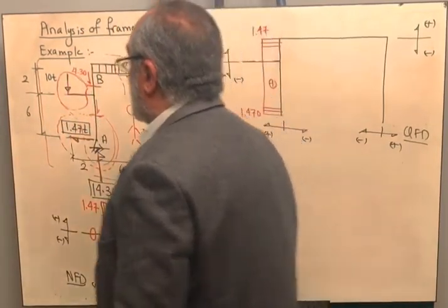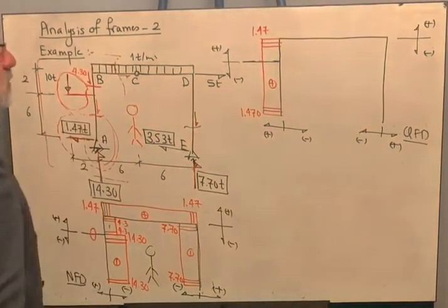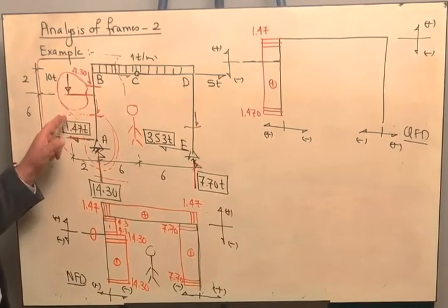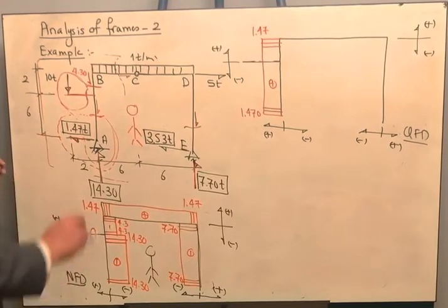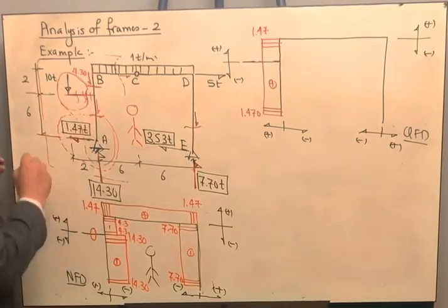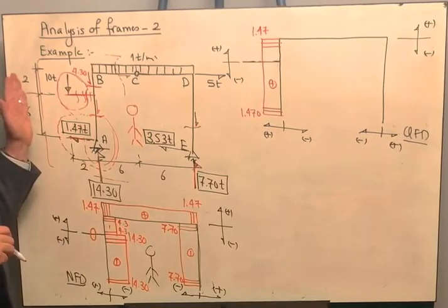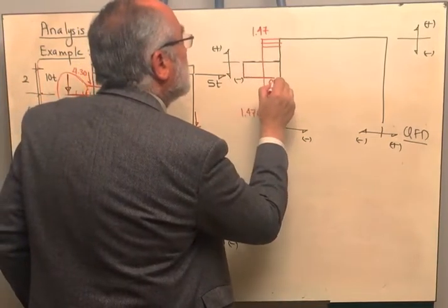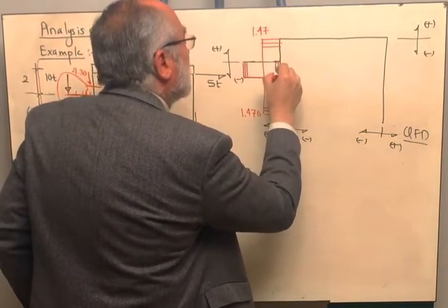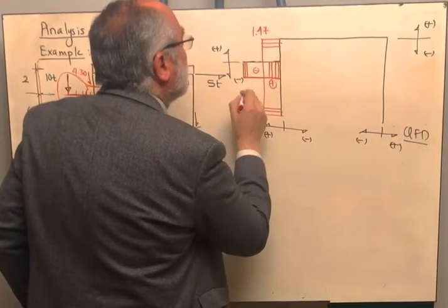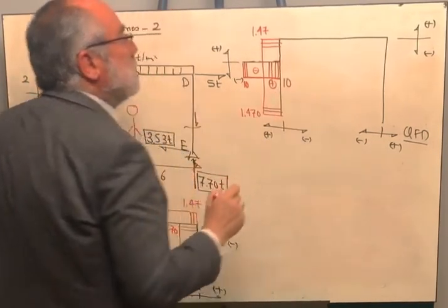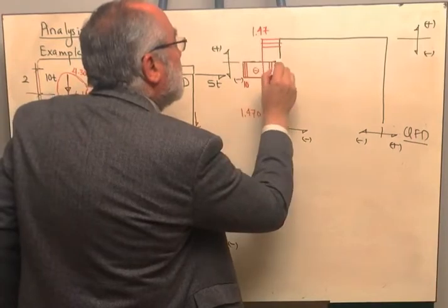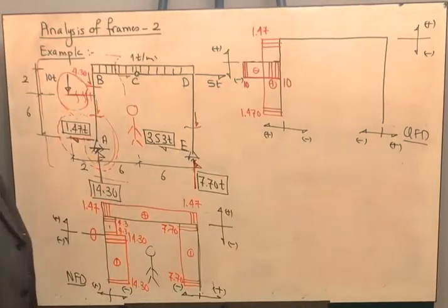Very good. Right. For the cantilever, I will start from the left. On my left-hand side, I am having a force of 10 ton downward. It is negative shear. If I'm taking a section here, or a section here, or a section there, and only counting the left portion, I still have the 10, which is negative. On this datum, it will be drawn below the datum like this. Don't worry if you are having interference in the diagrams, that's something normal in our work. So the central line or the datum is drawn in black, and the magnitude of the shear is drawn in red.